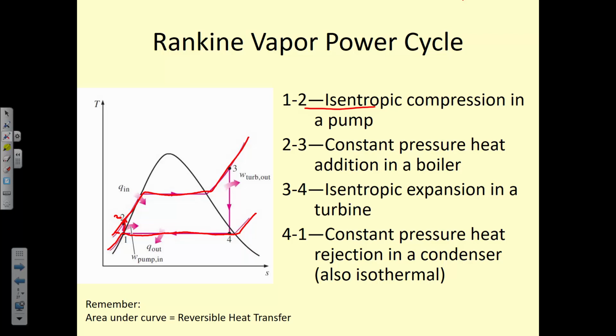So if we're going to look at the table in terms of pressure rather than temperature, we're going to have a very different value than we do if we look at temperature rather than pressure. So I hope that makes sense, but that's why when we make the compressed liquid approximation, we look it up at the temperature. So once we have compressed our liquid, we then add heat to it to evaporate it.